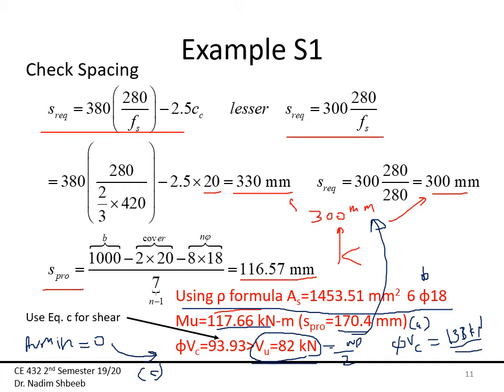minimum. Again, like I said, although we know in slabs the shear forces get redistributed, but still higher reinforcement ratio usually tends to lower the thickness of the slab. But again, we talked about that before. So just to re-emphasize, for shear calculation, number one, check V ultimate against phi VC, which is either equation A or B, and in this case I used equation A.